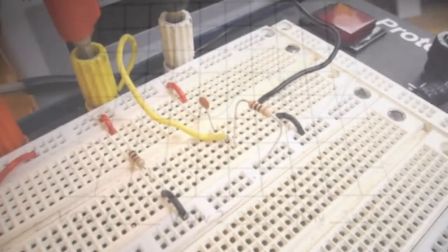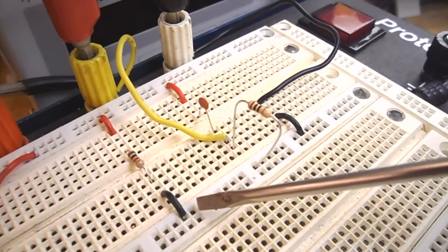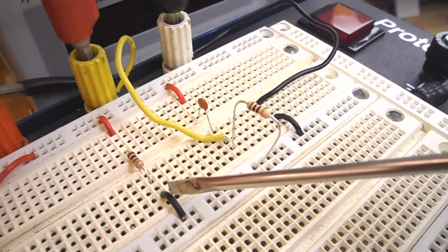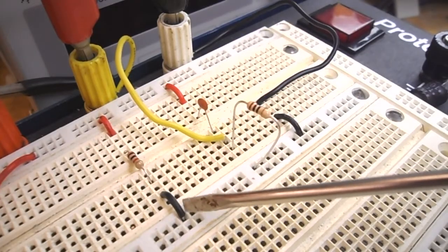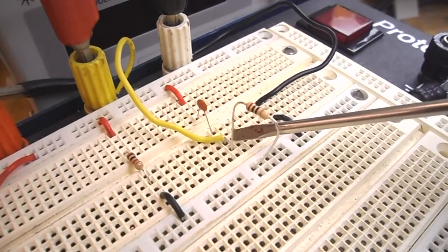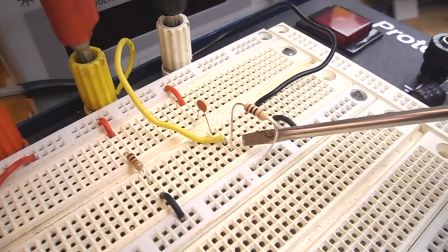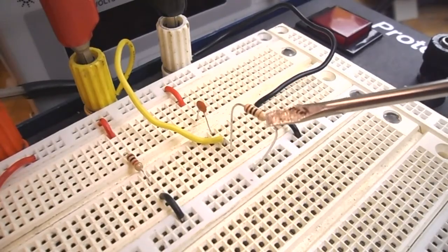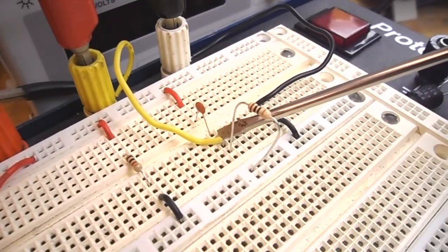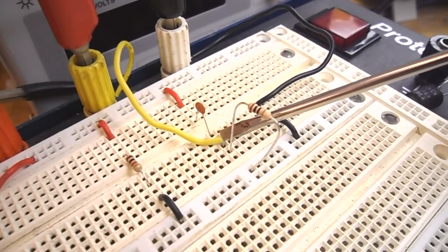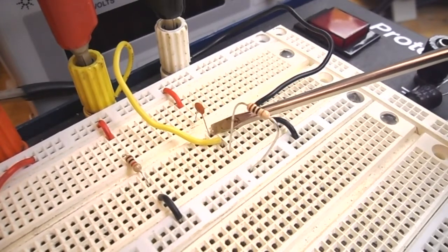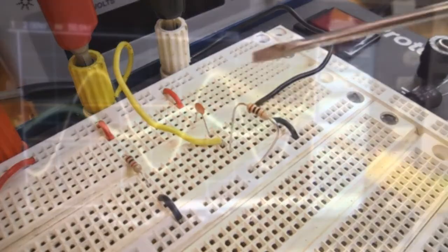So coming back to my circuit, I've taken the 10 ohm sensing resistor out from the 1K ohm resistor and replaced it with that little link that takes it back to the ground bus coming in. And I've removed the link that was going to my 10 nanofarad capacitor and put in my 10 ohm resistor, and moved my yellow wire, which goes to channel 2 of the oscilloscope, to the junction of the 10 ohm resistor where it meets the 10 nanofarad capacitor.